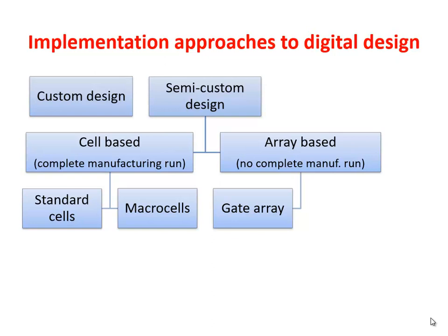Okay? In the gate arrays, actually, the only part of the manufacturing that has to be done is the top interconnect layers, because also the bottom interconnect layers have been already placed. But the top interconnect layers can be placed in order to design the complete circuits. So you have logic gates already fabricated, and then you need only to tell the foundries how to interconnect them.